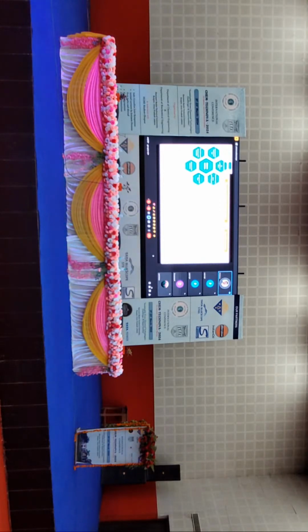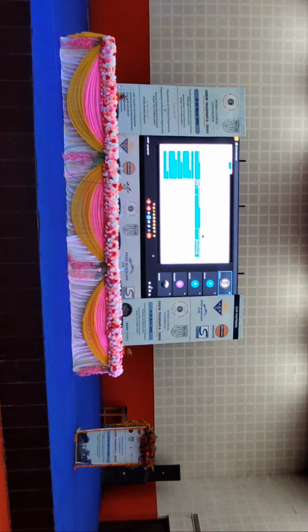In the previous case, I did not discuss it, but you can see how much time it is taking. If I use the AC wall, roughly 6 hours, this is around 12 hours, this is around 6 to 8 hours, this is around 7 hours. If I use the DC fast, then maybe 1 hour, or DC portable maybe 20 hours. So you can see why we are taking this much time to charge the vehicle. If I use the socket in my house, it will take 6 to 10 hours. Why is it taking 6 to 10 hours?